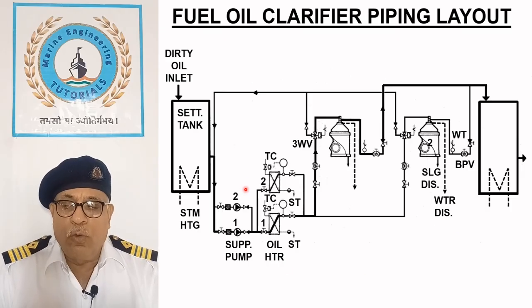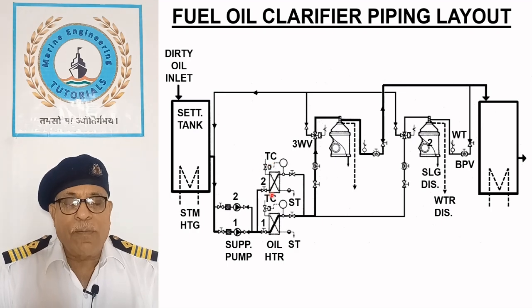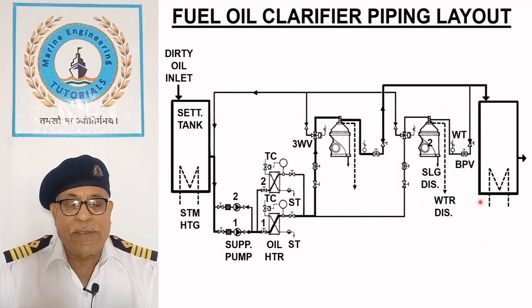Supply pump number 2 and oil heater number 2 are kept on standby. The supply pump suction filter is cleaned on a monthly basis.